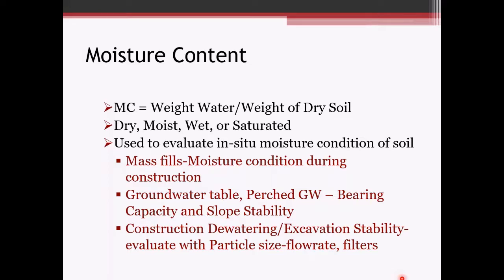It also gives an indication of where your groundwater table may be and if you have perched water layers, as well as aiding in evaluating construction dewatering and excavation stability, particularly to evaluate flow rates and filter materials.